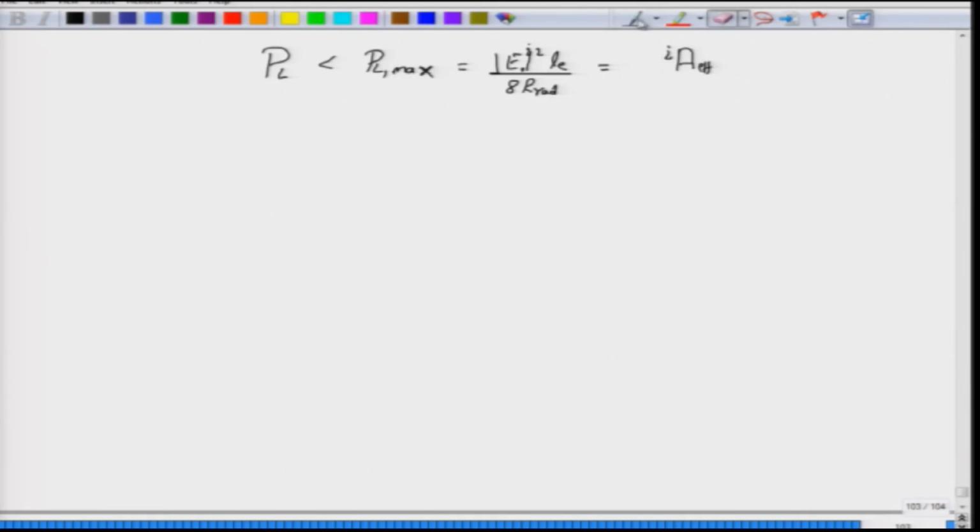Okay. We have not yet defined the effective area of the antenna, but it feels that the maximum power density times the effective area of the antenna should essentially be the maximum power that I can extract from this EM wave, right. So, the EM waves are propagating, you put a certain aperture, or the effective area, and this is the area over which the antenna is interacting with the electromagnetic field, and the larger this effective area is, the larger is the amount of power that can be delivered.